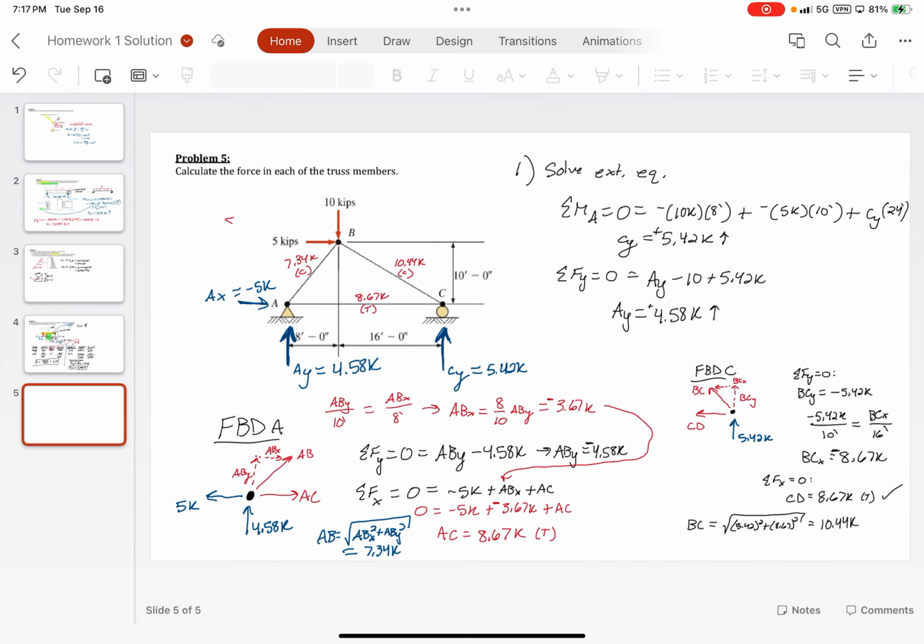Okay. So when you're solving for the moment, for the reaction for GY, you would do times 30, right? Because this part wouldn't count, right? So this is sum of moments. Where are you taking the moment from? This one is from F of Y. Right, but you shouldn't be multiplying any lengths.